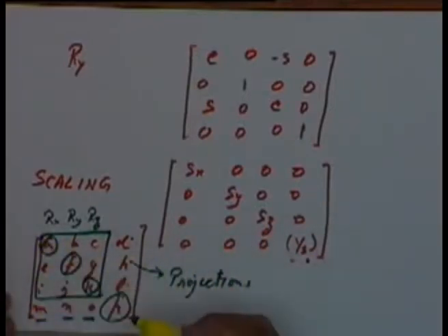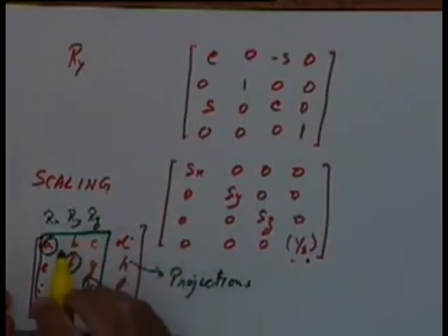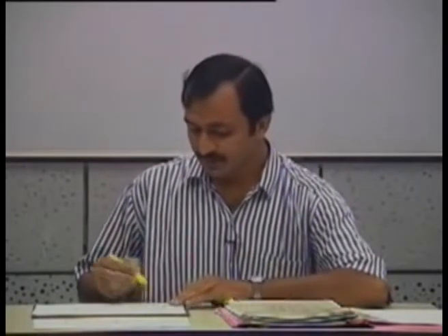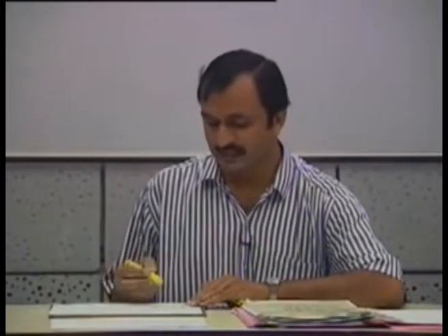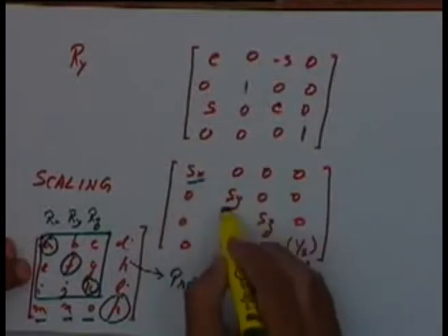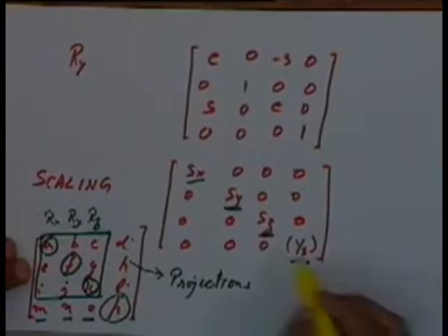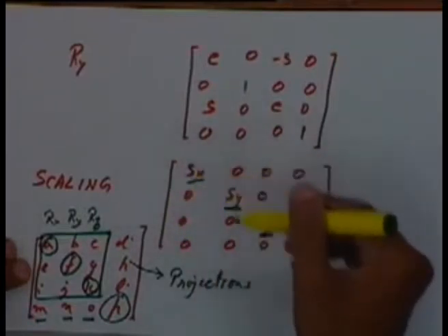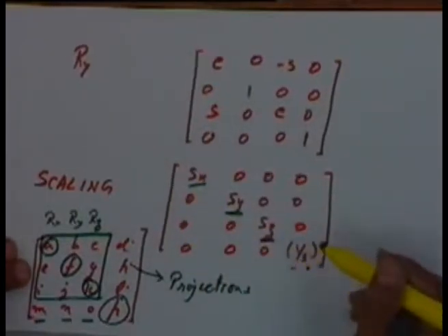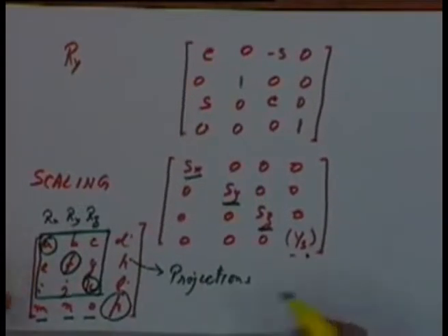Okay, so out of these 16 terms, these 13 terms will control the different transformations that we have already seen, that is translation, rotation and scaling. Then last time we also saw that if you want to reflect about any axis or about a plane, that can be done by changing the scale factors in the 3 directions. Okay, by giving either 1, 2 or all of them values of -1, we can reflect about either an axis, about a plane or about the origin. Okay.